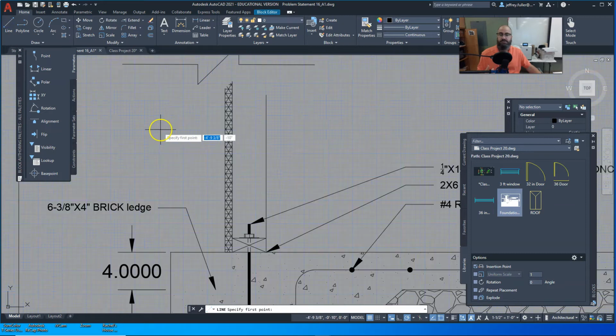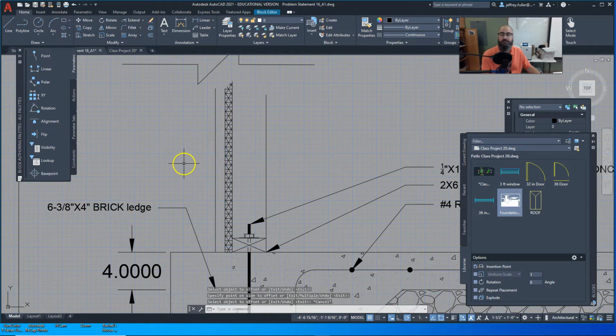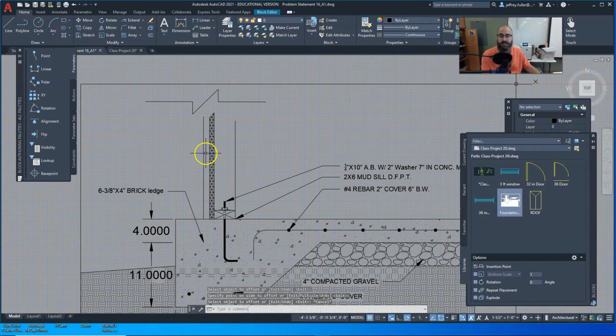Okay, we're just going to do a real simple vertical wood siding. We're not going to do anything special. And it's going to be 1 inch thick wood siding. That's a 1 foot offset. We need it to be a 1 inch offset. We're going to select this line, offset it. Okay, and then we'll come back later and we'll actually add a pattern to that.